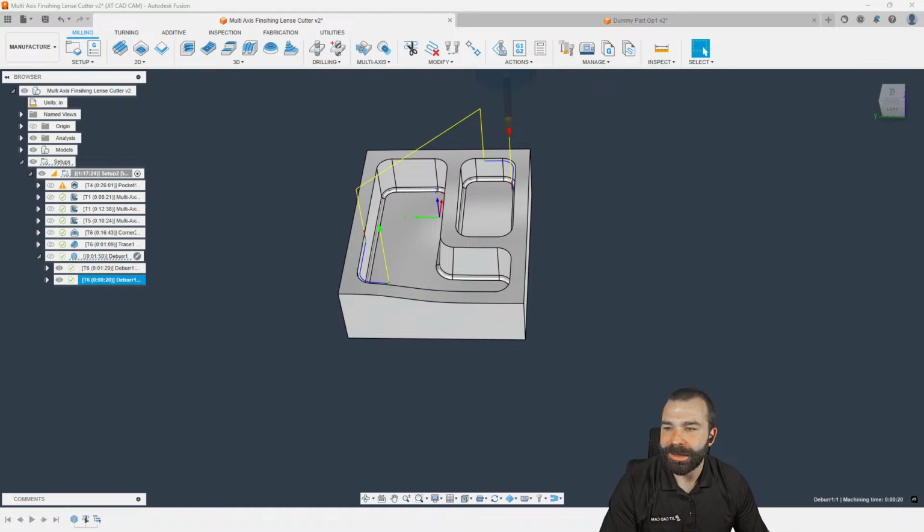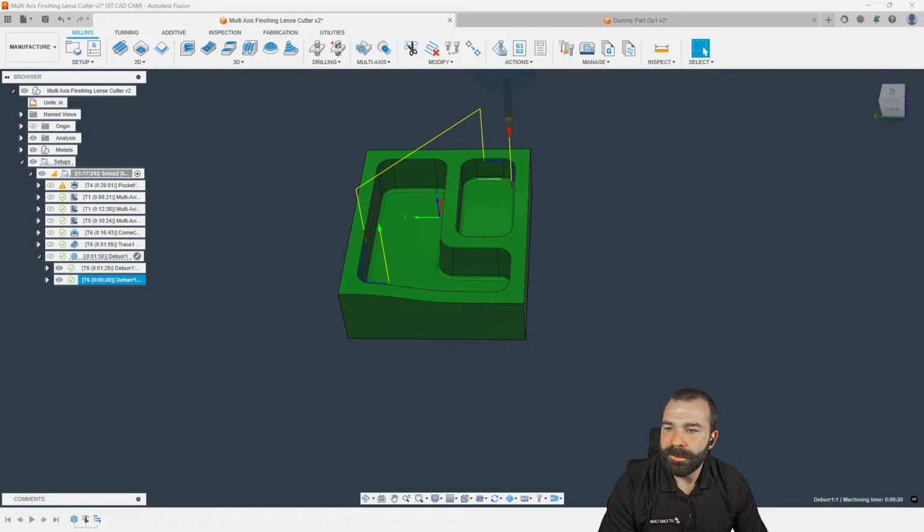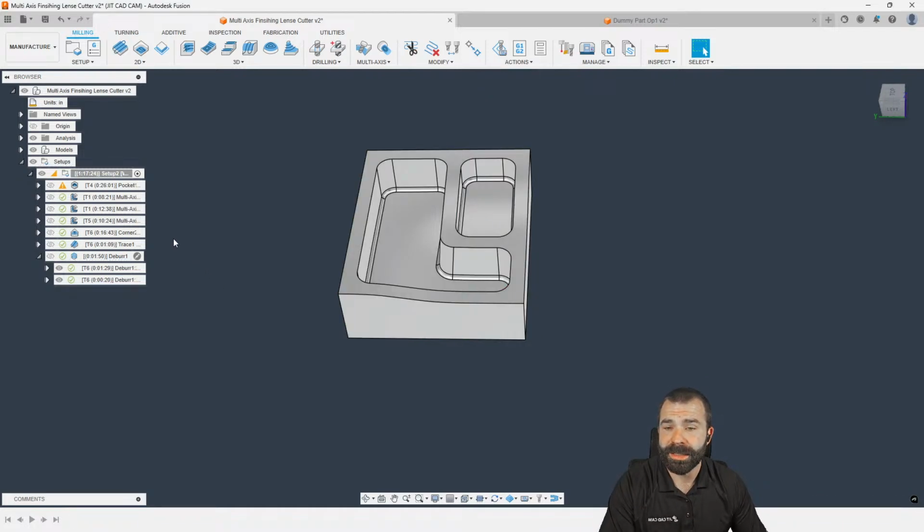With that, it looks like we got another question. Does Fusion have a way to force moving the Z-axis to max height after every tool change? Will this take a modification in the post? Well, Ken, overall, you want to move up to what I assume, so you have tool change position and then you have machine home position. And both of those are controllable at the end of the day.